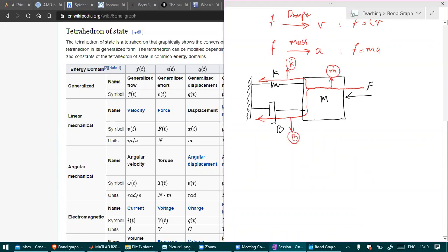Just pay attention that no energy goes to the wall unless you have a damper or spring behavior for the wall, or you have a sink or source or another force acting in the other direction. So when you draw the diagram of the system, just draw the diagram of flow of force, flow of power in the system.